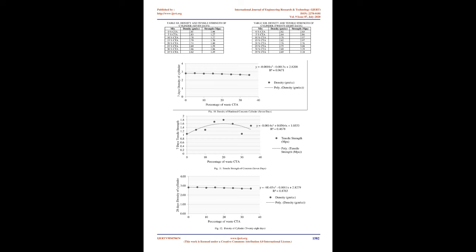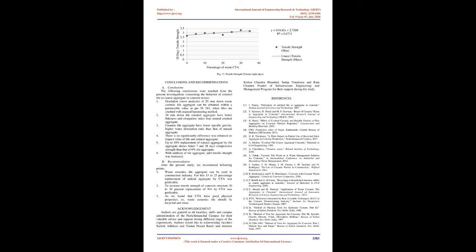Detailed data of grading of aggregates are presented in Appendix I. Water absorption and specific gravity. The specific gravity, water absorption value and water content of different mixes were tested in the lab. Obtained data are shown in the table below. Ceramic tile has a higher water absorption value. Due to high water absorption by CTA, the W/C ratio will increase proportionally with CTA percentage.